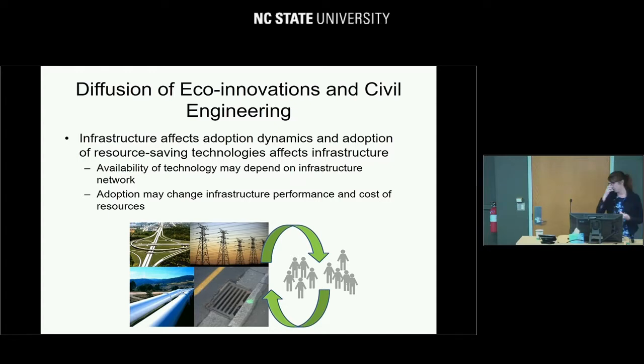For example, there's a study of a city in Europe where water reuse technologies were used, and the discharge to the wastewater sewer system decreased so much that the velocities decreased in the sewer system, and the solids and sediment were settling in the system, causing the infrastructure to fail. So we see there's this feedback in certain instances.